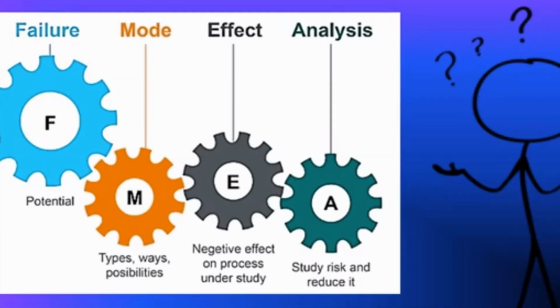And this upfront review and completion of FMEA protects you from any crisis situation later on. FMEA is a living document, and the FMEA should regularly be reviewed, and it should reflect all the latest changes and action. The other important point to consider here is that FMEA is also not a standalone document, as output of FMEA can be used as an input for subsequent product development process.